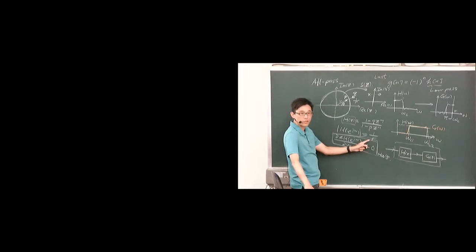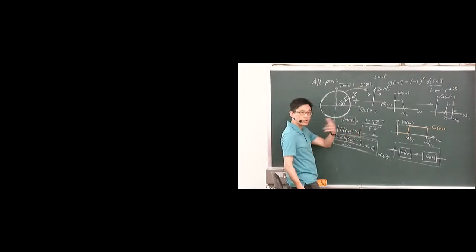That was using algebra. But this time, I would like to introduce a geometric interpretation. Why, when we let the frequency increase and let z go around the unit circle, does H(z) have a ratio that is always 1 over r? You can use high school geometry to prove that. So we'll begin with that.